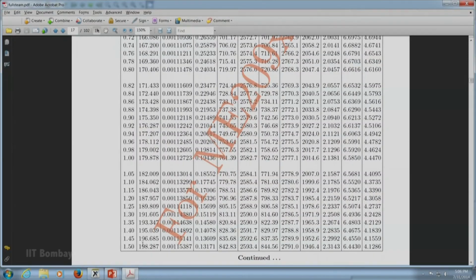That means the temperature there at 1B is more than Tsat. When temperature is more than Tsat, we are sure that it is in a superheated vapor region, and therefore one state, 1A, is saturated liquid, which is maintained at 198.287 degree centigrade, and the other state, which is also at the same pressure but at 250 degree centigrade, is in a superheated vapor zone. You can see the mixing of these two zones. This mixing of two zones, a saturated liquid and a superheated vapor, 1A and 1B, two states together, they get mixed.